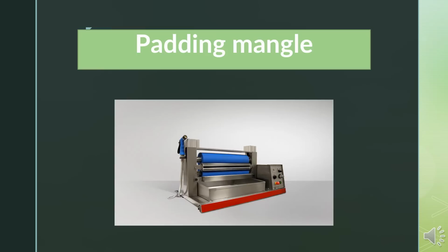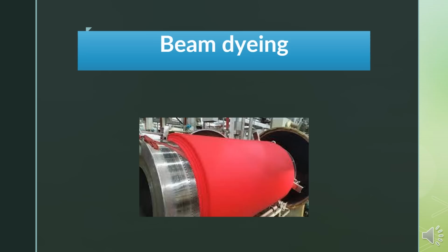After this heating chamber, there are a series of washes, some of them with only soft water and others with soap solutions, to remove the excess dyes and accessory chemicals that may still be left on the dyed cloth, thereby improving fastness. 4. Beam dyeing.